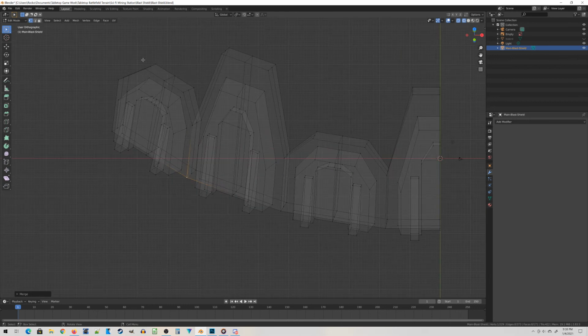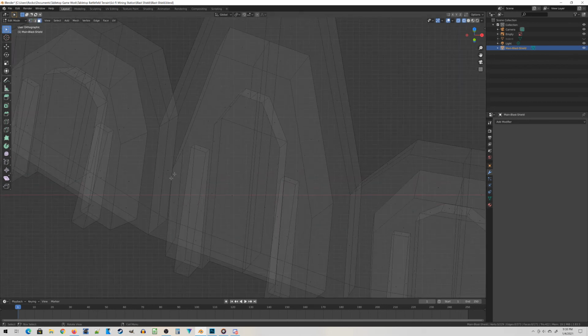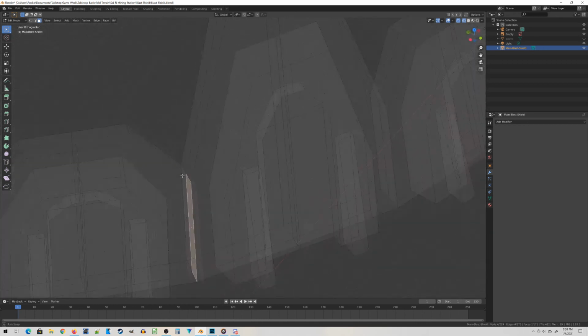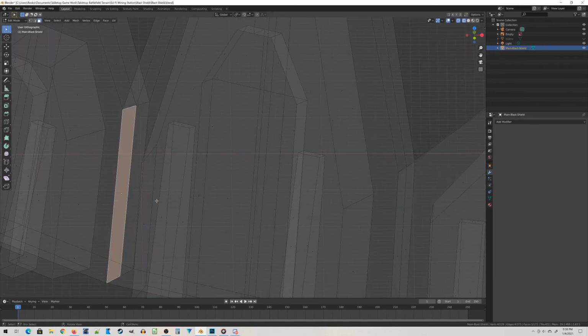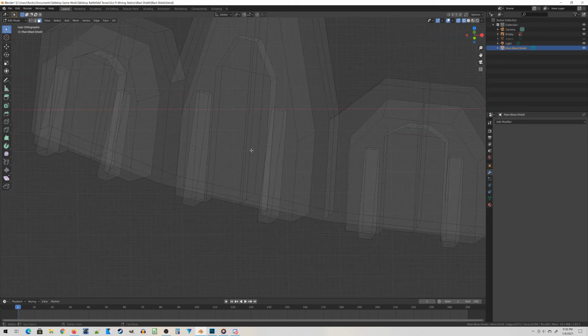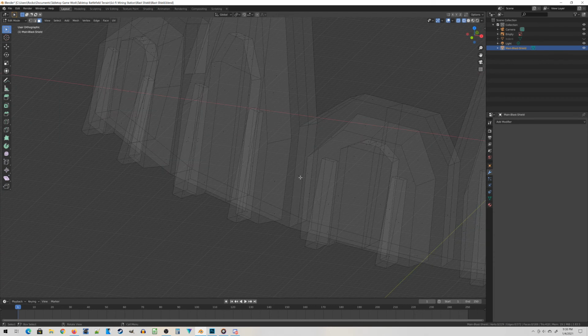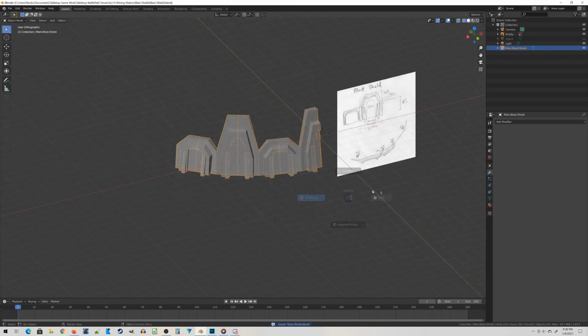We're going to jump into wireframe mode, go over to face select in the upper left hand corner. And these little black dots right here are how you select a face. You can see how that one's inside between the 2 segments. That's an interior face. It has to be deleted. Press X, choose delete faces, repeat the process for the one next to it, and there should be 2 of those to reach these intersection points.